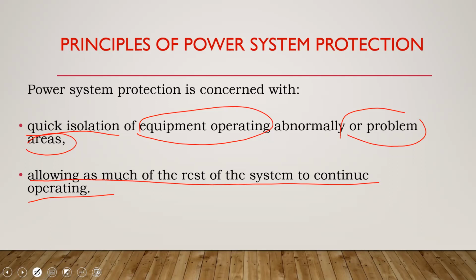So you can have a problem on a single transformer. And if the breaker associated with that transformer doesn't operate, then instead of taking out a single circuit, it may take out the entire substation. So you'll move from power being lost to a few hundred customers to a few thousand customers. All right? So keep that in the back of your mind as we continue the discussion on protection. Any comments, questions so far?